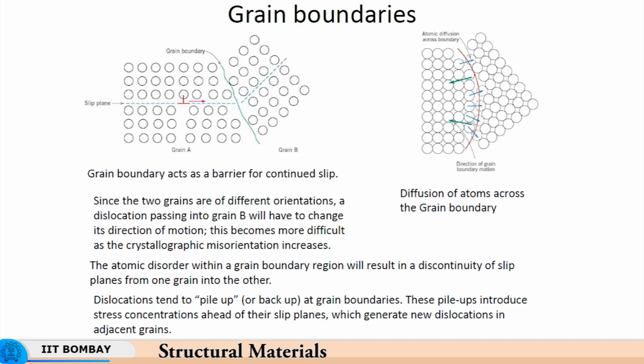But then dislocations are continuously being generated because more force is being applied. The impedance of the interstitials and fellow dislocations is being overcome by application of an increasing amount of force. And this increasing amount of force on a macroscopic scale is called work hardening.